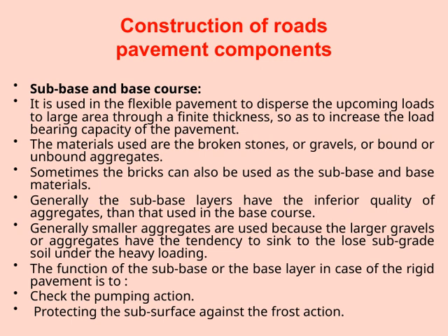So these layers are not just about supporting the pavement structure. They also contribute to its durability and longevity by addressing specific challenges like load distribution, frost protection, and preventing pumping. Overall, a well-designed subbase and base course are vital for constructing durable and resilient roads.